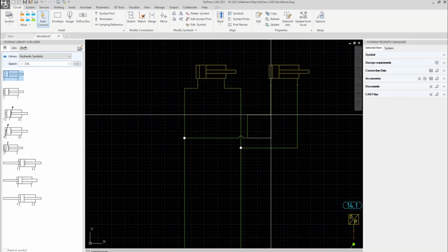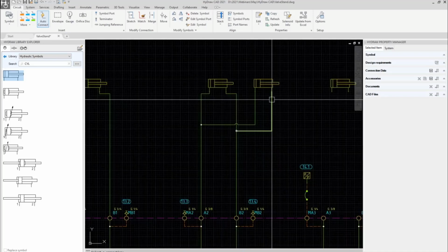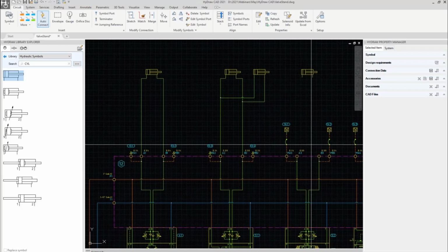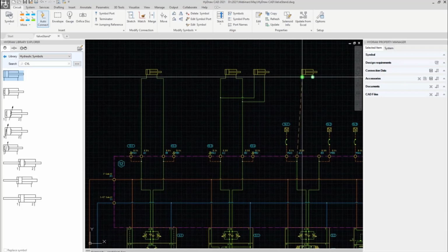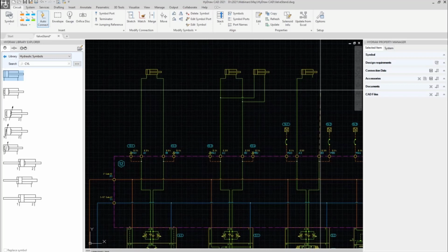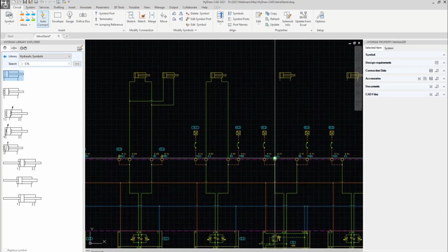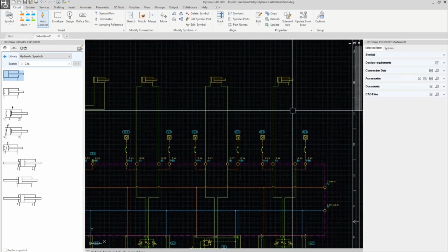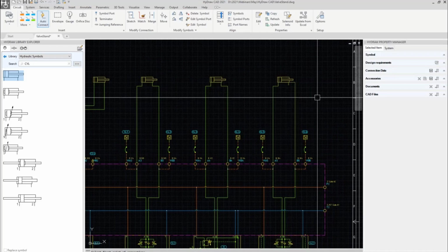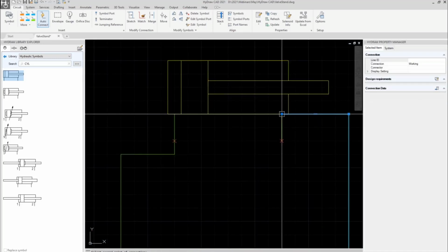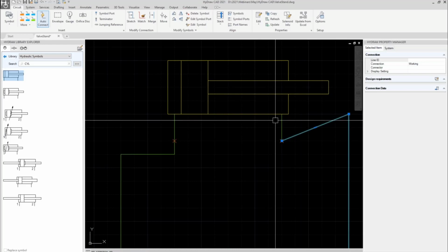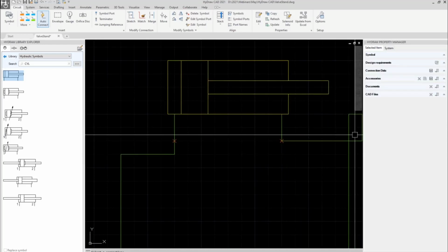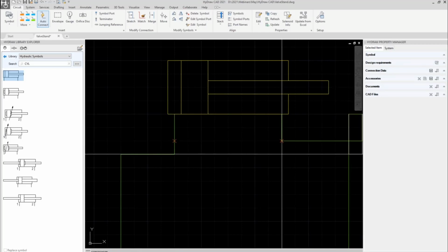You can also use stretch to remove those bends from the connection line. In this case, if you pick a wrong item, just take the insertion point, connect, and always use the stretch to simplify the connection line.